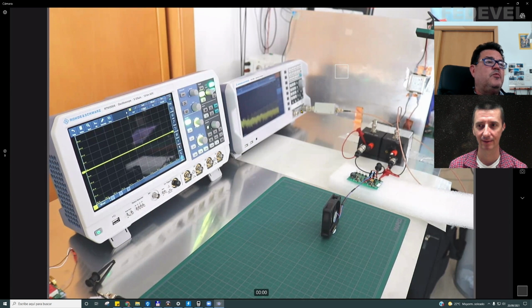You can find some instruments with some kind of attenuator or protector. Really, I think these instruments don't have protectors, but you can have some attenuator that you can connect or disconnect if you want. But any kind of element you introduce at the input port is a limitation for the dynamic range of the instrument. You will not be able to measure very small signals. And this is a problem because when you are measuring very small signals, you don't need this transient protector. So it's better to have this externally.